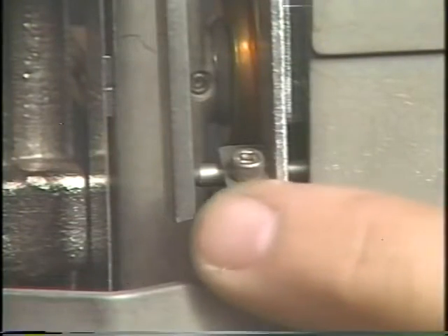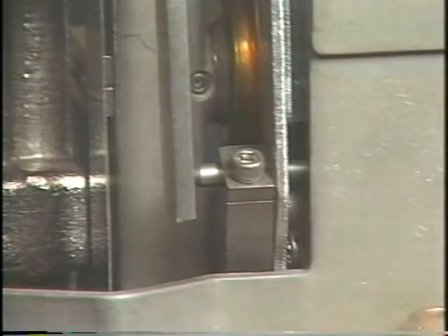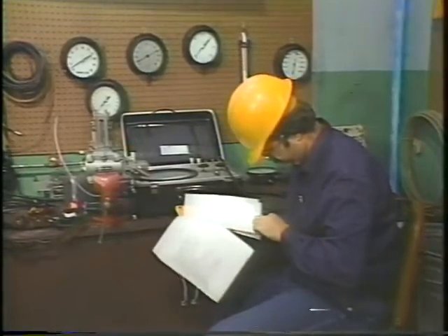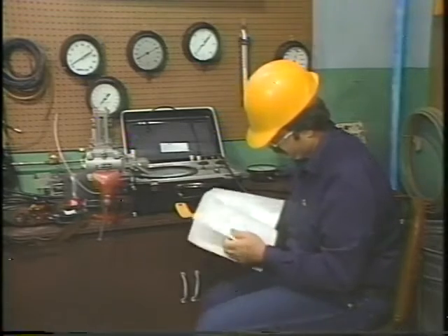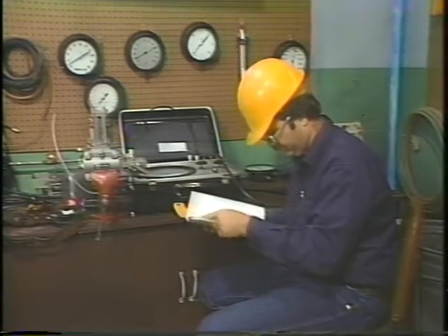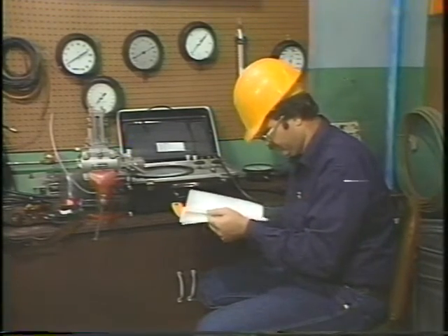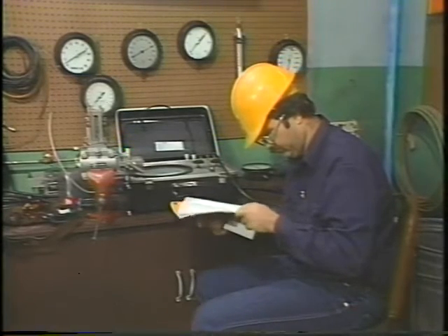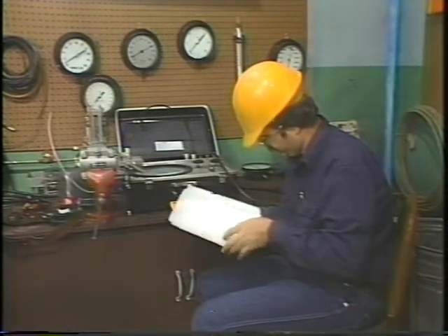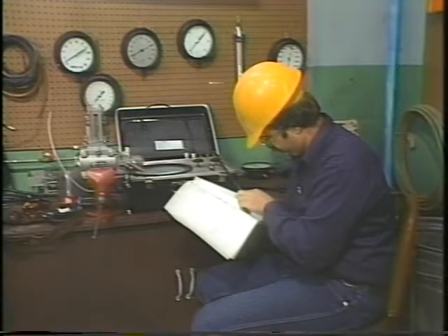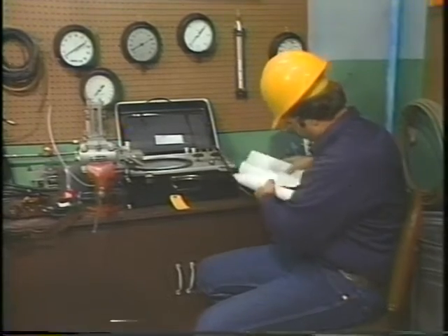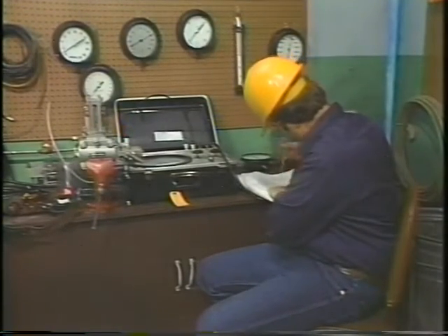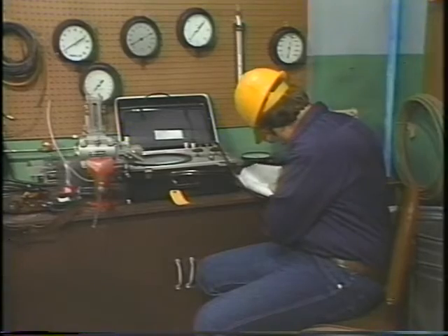Uh-oh, they're not parallel. Since they're not parallel, that'll keep the error detector in this transmitter from reaching its maximum back pressure. It looked like that nozzle was worn a little bit. I'll see if they have a part number for that nozzle. Let's see, it's back here in the parts list. Yeah, here it is. It's part number 1907204. And I'll have to see if we've got one of those.